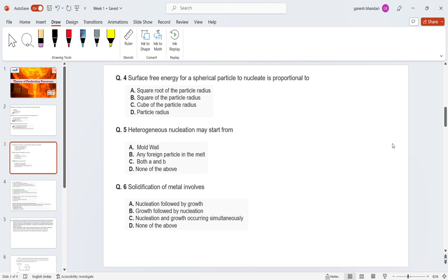So just pick one particular thing, like lead and tin, to understand anything. Pick lead and tin, and then study its solidification behavior. Then all your solidification concepts will be clear. Then read how the solidification of lead and tin is different from other alloys.